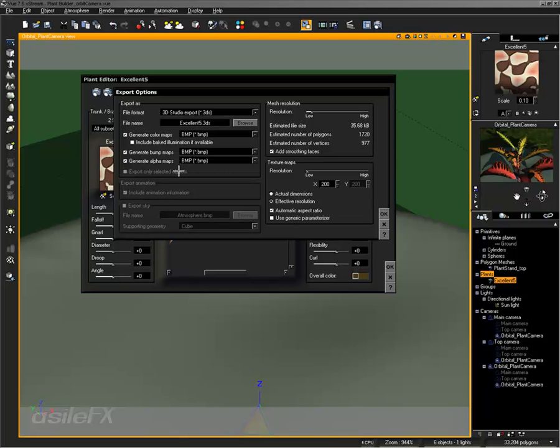Now the alpha is actually the transparency map. It is called an alpha map because it may be used as an alpha in other applications, but it's not necessarily the alpha that is part of the plant, because there is an alpha output, but most plants in Vue, or pretty much every plant, uses the transparency rather than the alpha output, which is why you also have settings based on white being clipped out, black being there, rather than it being an opacity amount, where white would be what remains. Now the texture maps of this aren't very large.